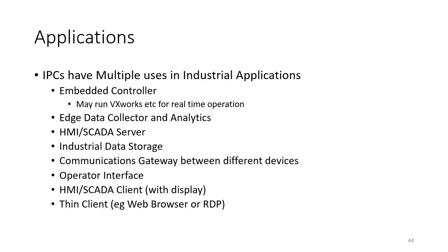But those embedded controllers, they often run one of these real-time operating systems, and then on top of that would be some sort of real-time application development language, or maybe you would be running one of those languages we just talked about recently. But common languages, there would be the PLC vendors who have their own programming capabilities, and then there are more open programming applications like CODESYS and so on, which let you run IEC 61131-3 languages on top of an embedded controller.